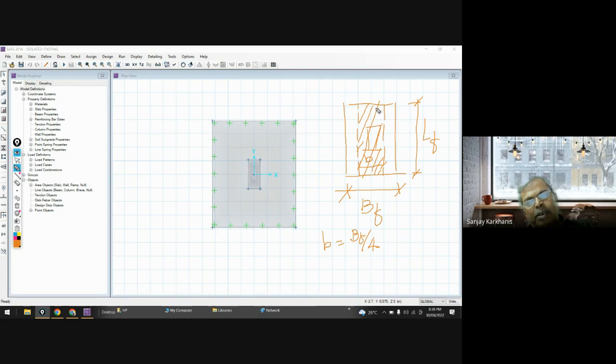Normally, this is the area of reinforcement where you have to provide for maximum bending moment. So maximum resistance is to be provided in this area, and in the remaining area you can provide half the reinforcement. That is what the book says, and the same thing happens in this direction also. But for simplicity, we go for the same reinforcement over the entire area.